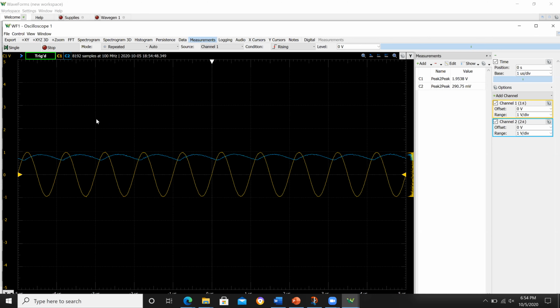So what's happened? Well, we've exceeded that frequency, and as you exceed that frequency, your gain rolls off. So the gain of the circuit has substantially dropped off. And we're actually seeing some distortion now. We're seeing 2 things here. We're outside of the gain bandwidth product of our op amp for what it's configured for, and the op amp has likely hit a slew rate condition where the output can't keep up with the input.